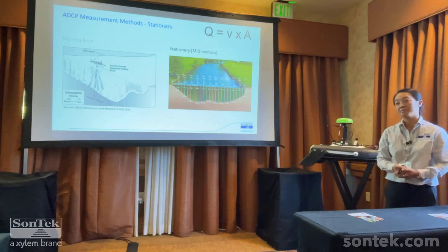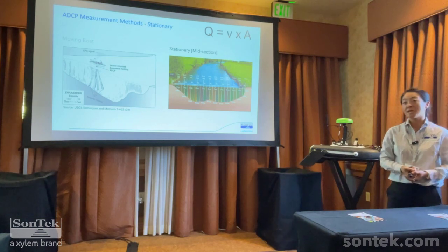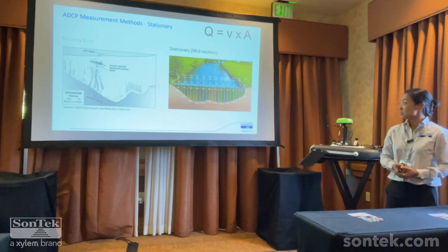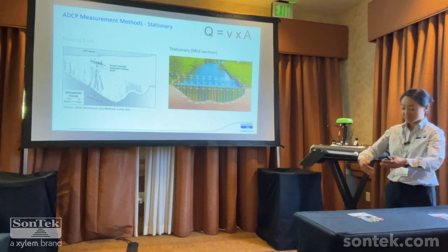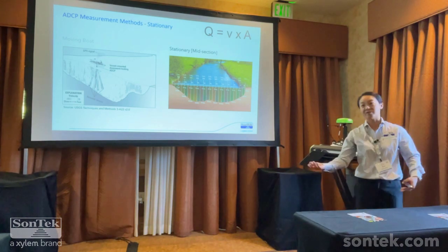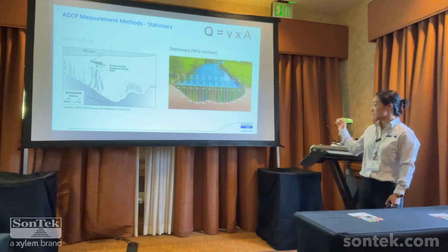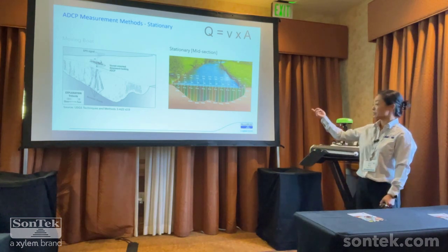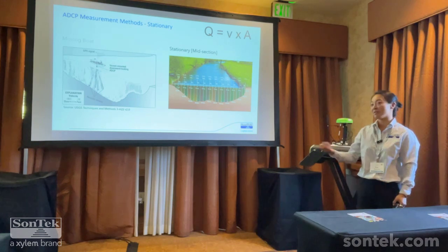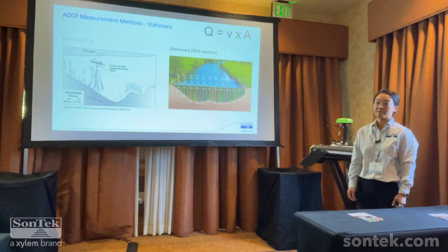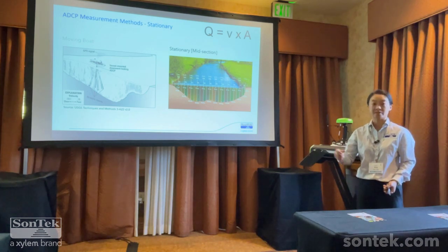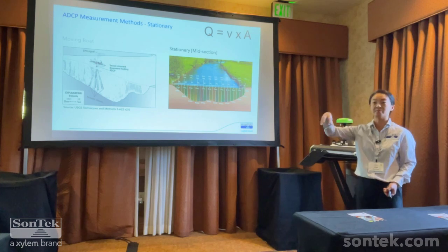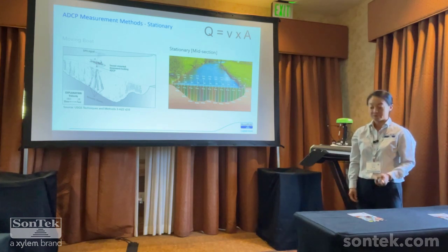Yes? So you're physically in the water with the unit with the stationary method? It actually depends. So with an ADCP, we actually don't recommend that because one of the beams could accidentally hit you or whatever. So in an ADCP situation, people will be doing this with a tether or off a bridge or whatever you can figure out. There are also remote control boat options where there's like a loiter mode where you can just loiter and the GPS on the remote control boat will control that loitering situation.